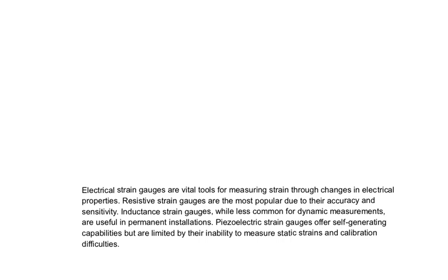Piezoelectric strain gauges offer self-generating capability but are limited by their inability to measure static strain and by calibration difficulty. By this, we will end the electrical strain gauge. These are a few summary points I discussed at the end, so you can remember the different types of electrical strain gauge.